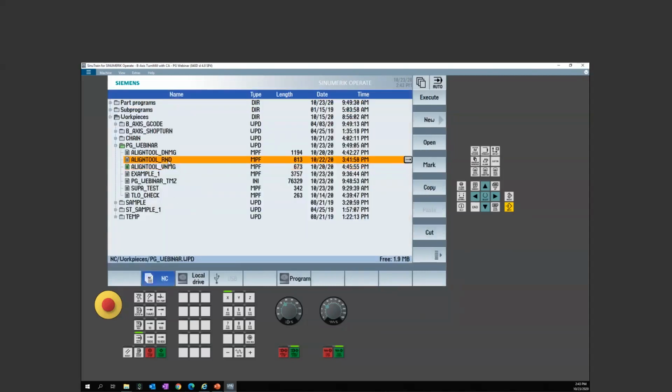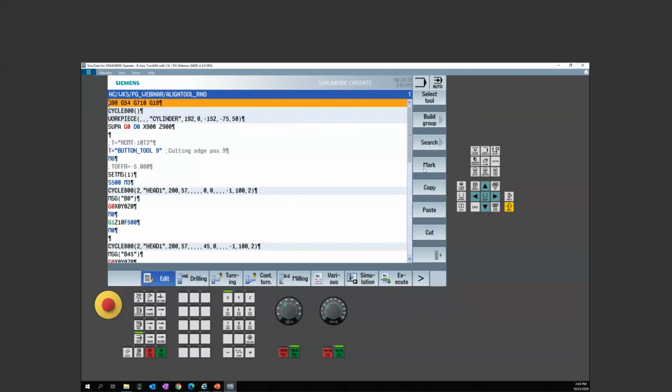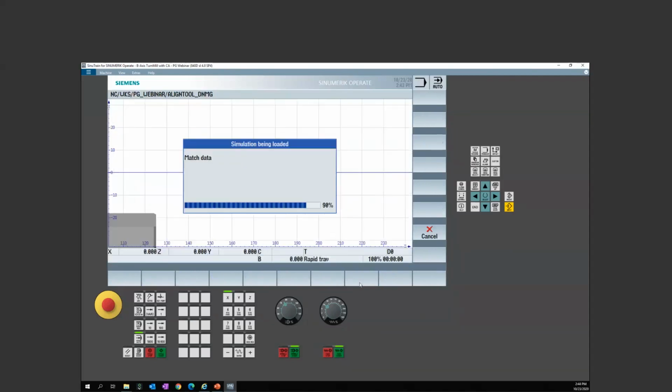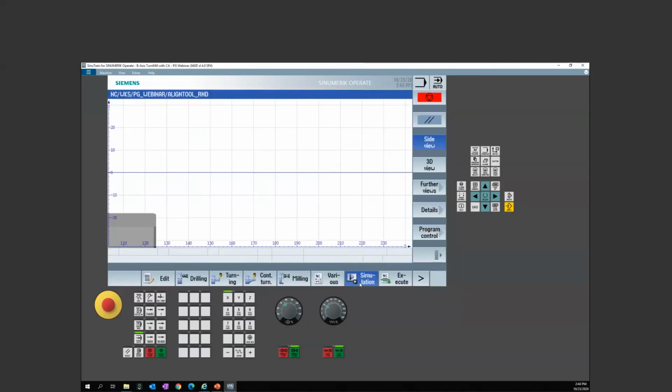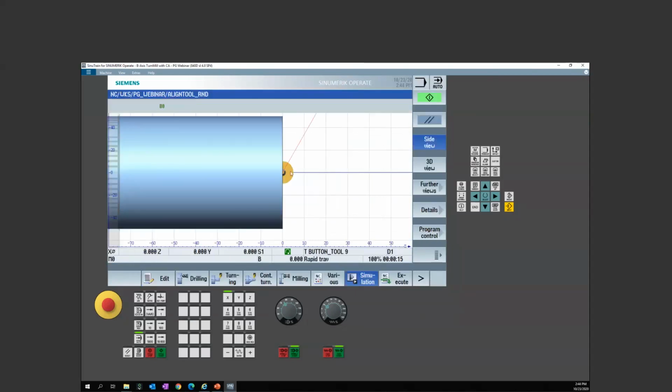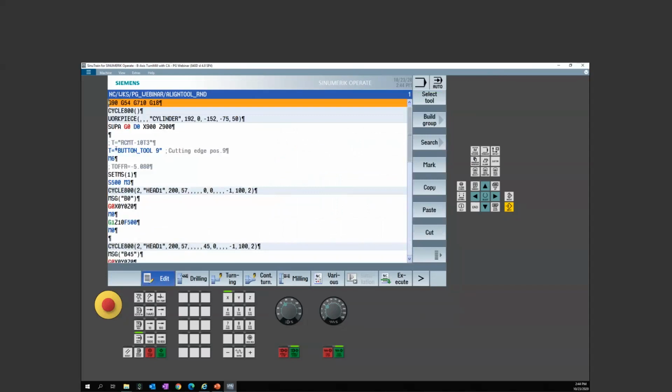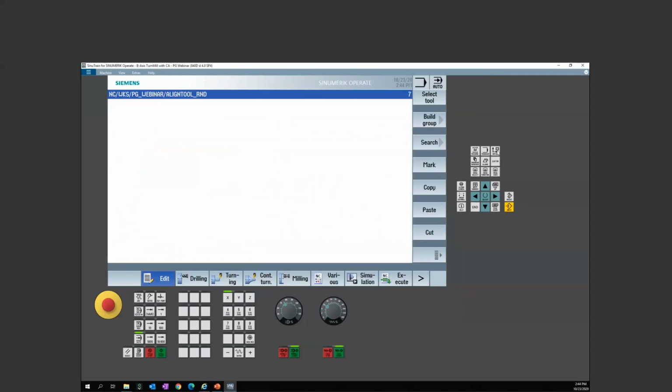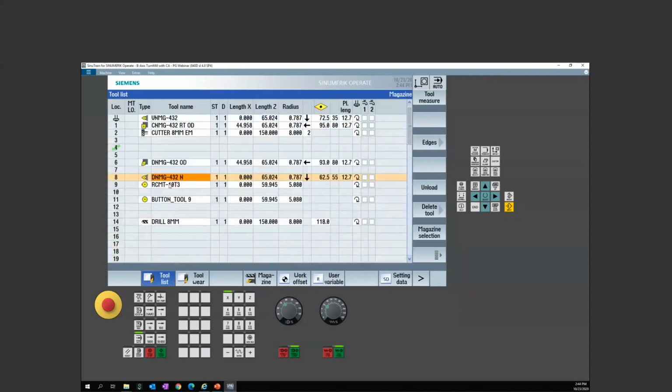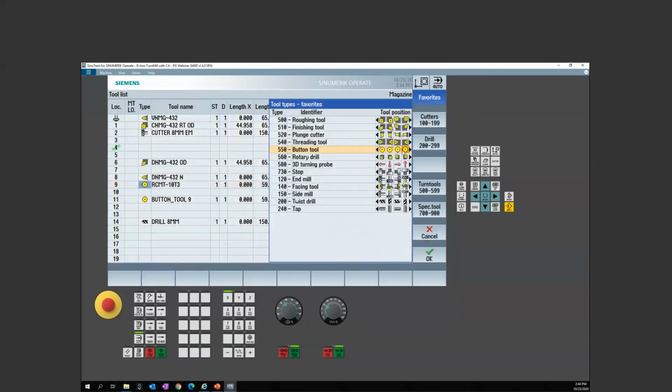So here we have a round tool. If you looked at it in graphics, it would be kind of hard to tell where the insert orientation or the holder is. But in this case, at a B0, let me reset this, I'm getting ahead of myself. First, I want to look at it from a normal definition. So if we looked at this tool, there's my RCMT, I called it. You notice that when I define the tool, I'm using the orientation where my insert is going to be touching this edge. That's that little indicator. Hopefully you guys can see it. I know it's a little hard to see.